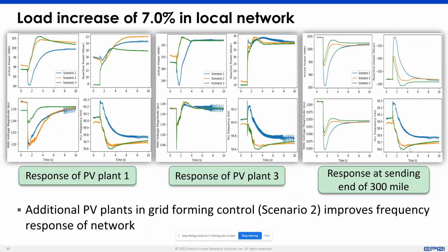In all these studies that we do, we start taking random combinations of the grid forming capability because we've seen that they have similar performance across the various kinds of contingencies. We also want to see if there are different types of grid forming in the same system, will they interact with each other? There are cases where they start interacting with each other. But in this one, it was just randomly mixed.